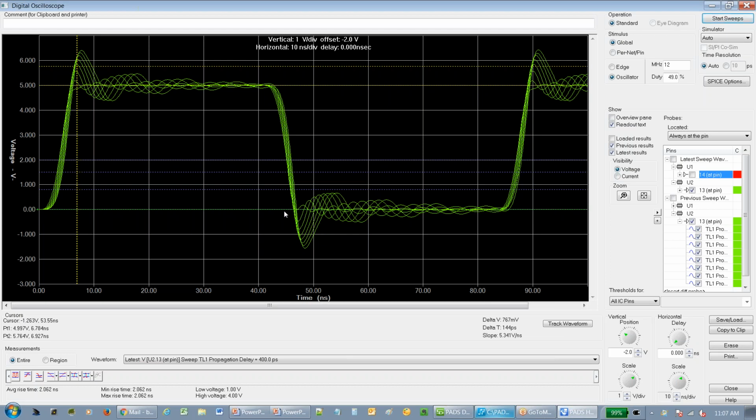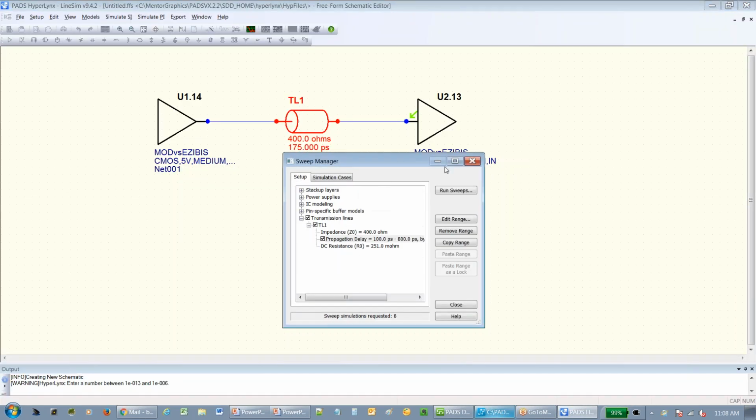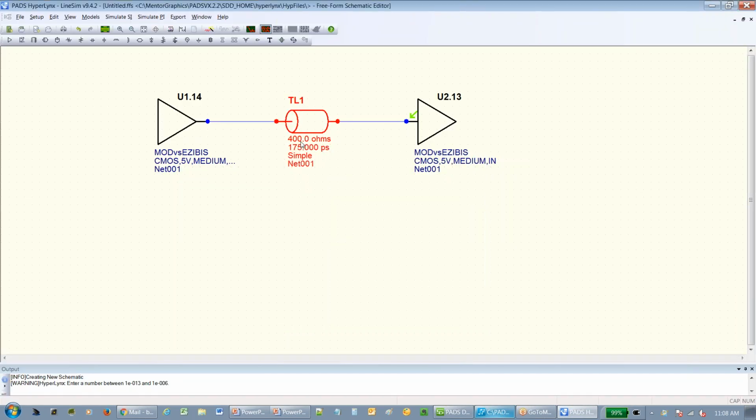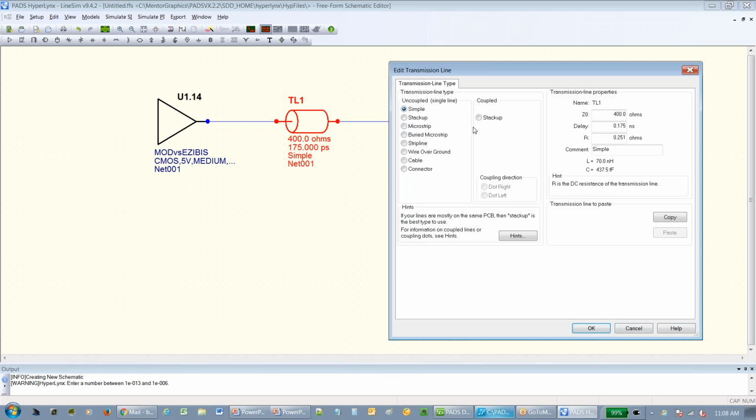And these are the things that I'm trying to educate people on in this webinar: you may not realize it, but these are the types of things you could see on your board. If you're not looking at the digital signals on your PCB for signal integrity, these are the types of things that could be occurring and you don't even realize it, okay? So this scenario that I put up here is for a 2-layer board. The impedance of a trace at 400 ohms would be like a 2-layer printed circuit board, okay?